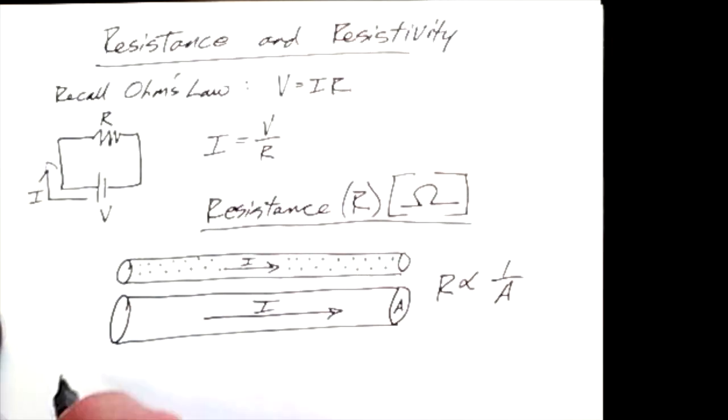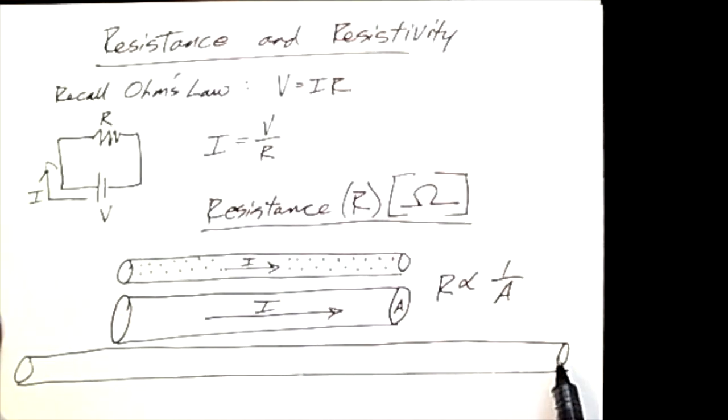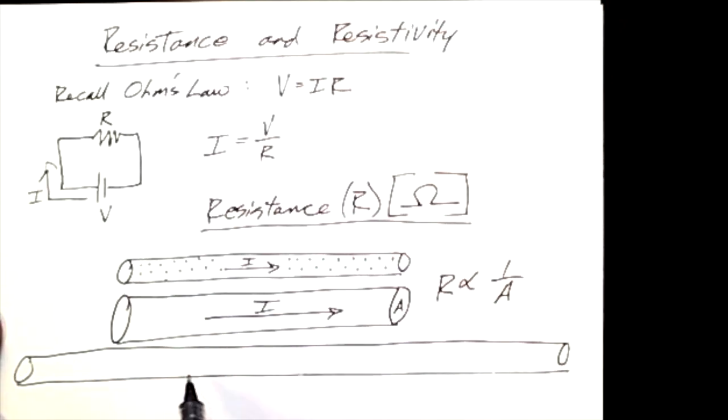And so it's important to recognize that if I were to extend the overall path length, where I make the length of the actual physical wire longer, then going from here, my original diagram, to this one, then we expect that the current might actually decrease due to the fact that as it collides, it loses energy, and the more length there is, the more likelihood or probability there is of those collisions, which means there is a higher probability of a reduction in current. And so in this case, we see that R is directly proportional to the length